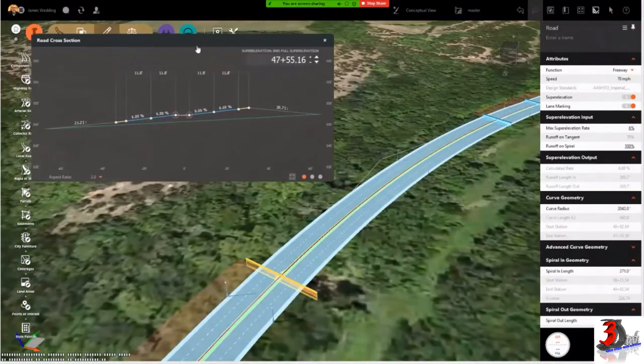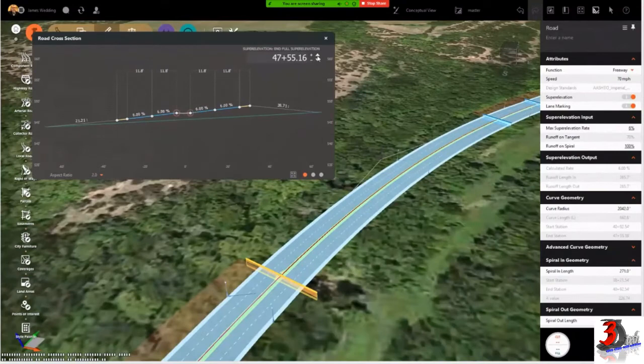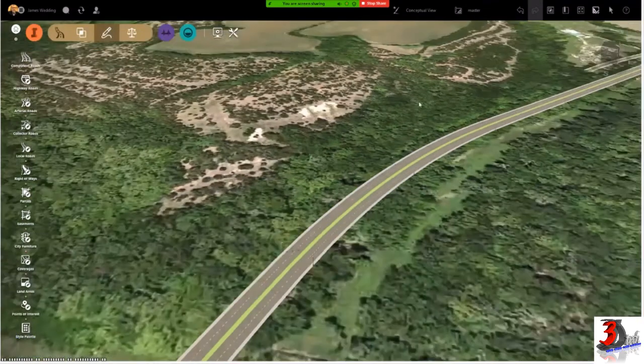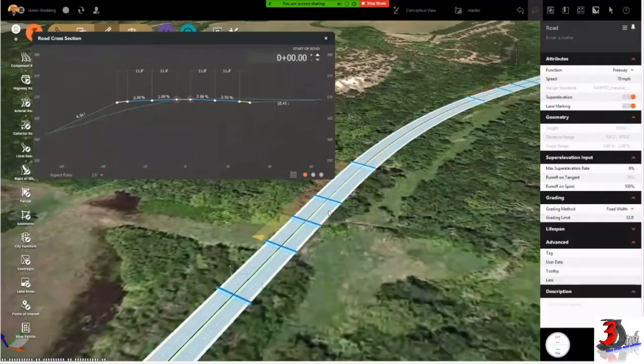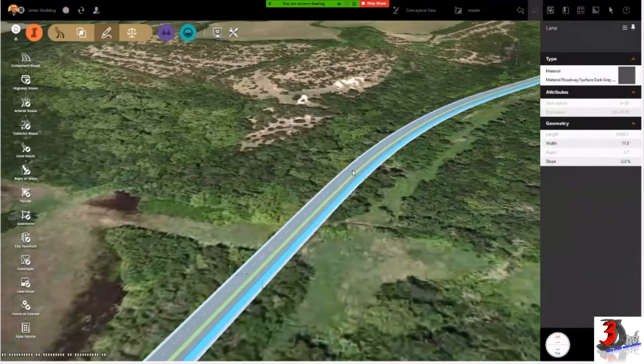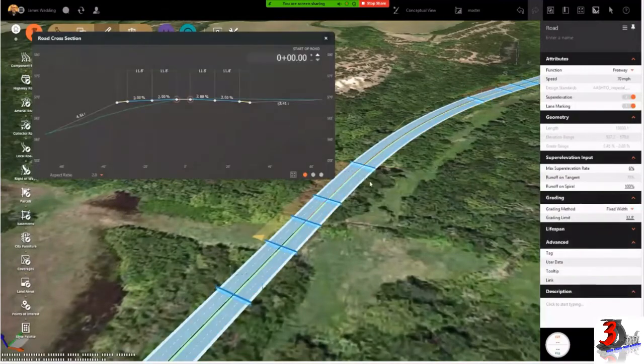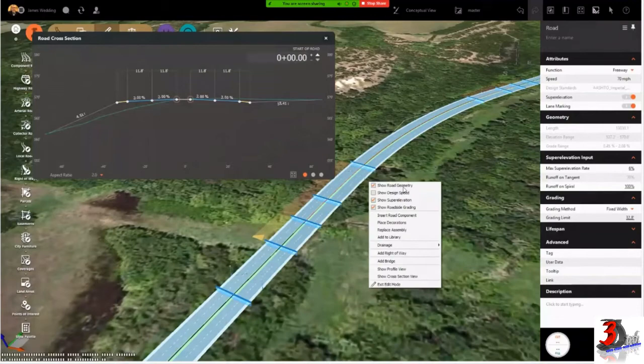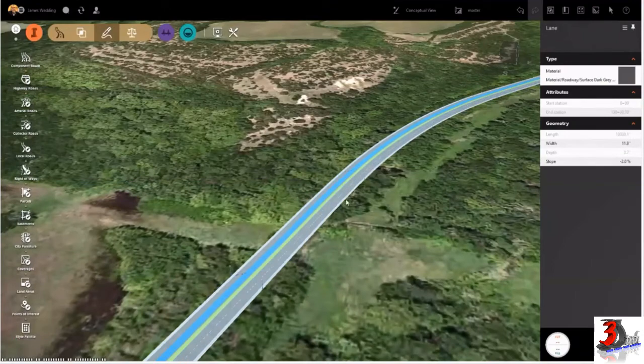If you click one of the slices, it will display the road cross-section for the current road. Sliding the slice up and down, either manually or using the arrow in the profile section view, you can see the road design update as it rolls through the super elevation. If you want to get a better feel, you can also begin to look at the volume of the road design. We can use the section editor, as well as see how it is impacted by changes made to the geometry.